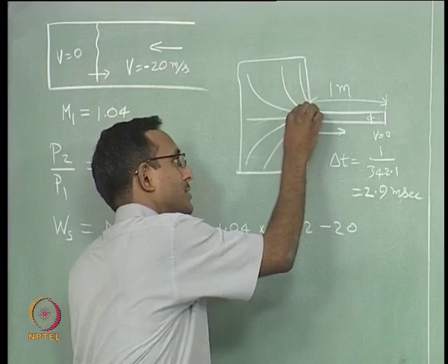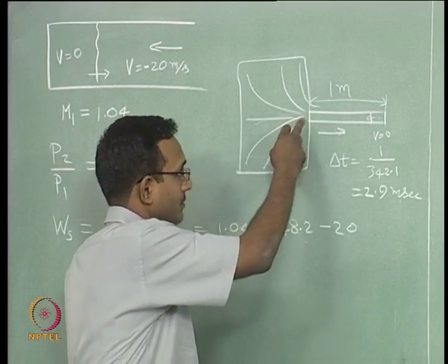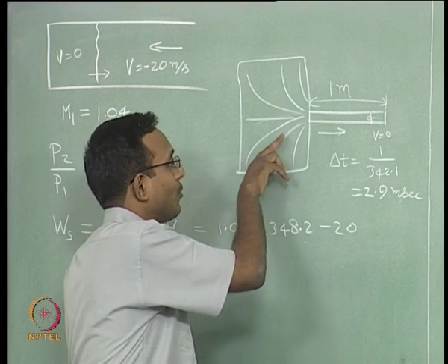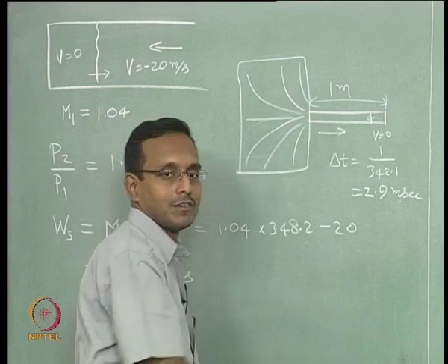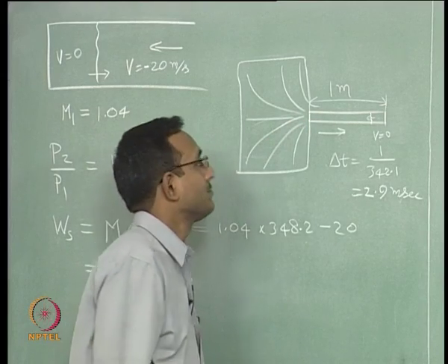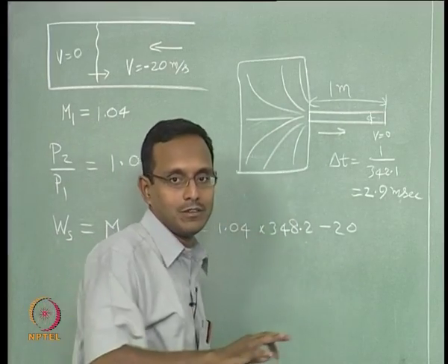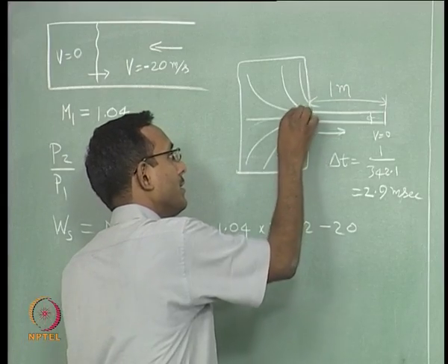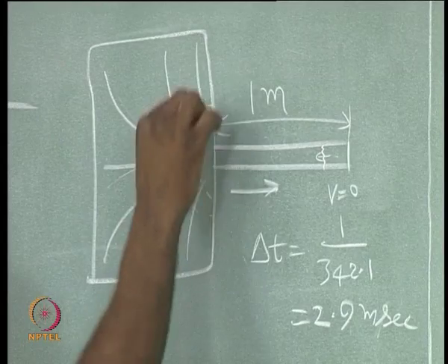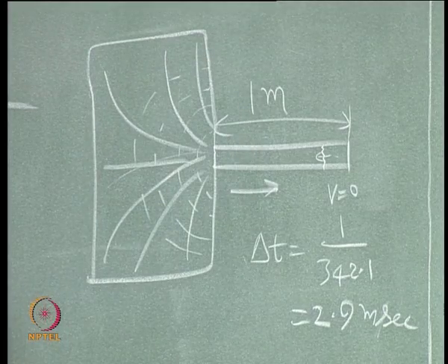When the shock comes to the exit, it does not stop, because if it stops here, what will happen? The flow from here will keep on going, it cannot stop suddenly, it will keep on wanting to go there. That cannot happen. So, this shock has to go and tell all the fluid that it can ever encounter that there was a problem there. So, it will keep on going in and it will go like this. It will start expanding to meet all the fluid elements possible.